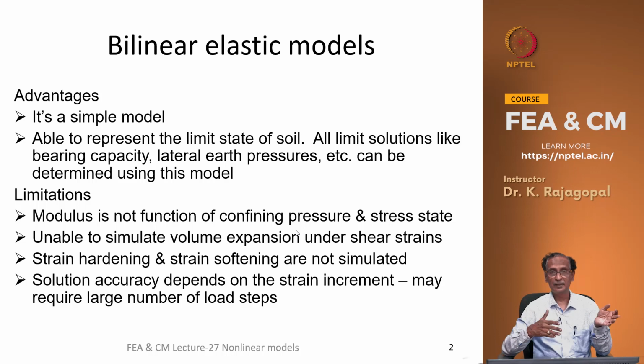And we have seen with some numerical examples of the simulation of the triaxial compression test that with coarse strain increments we over predict the limiting stress by an order of even 50%, 60%, and to get reasonably accurate results we have to use very small strain increments, and that will increase our computational effort and also the time.